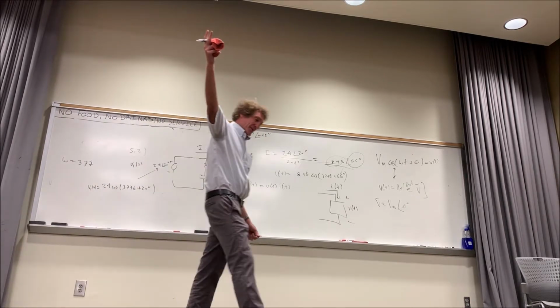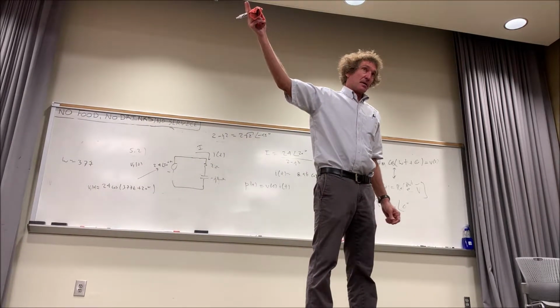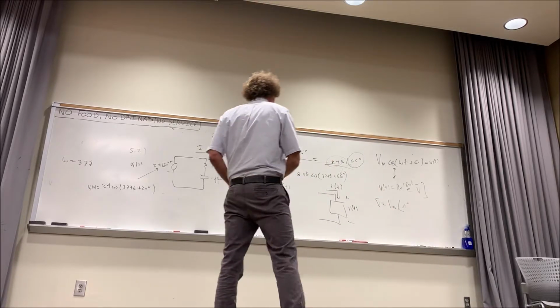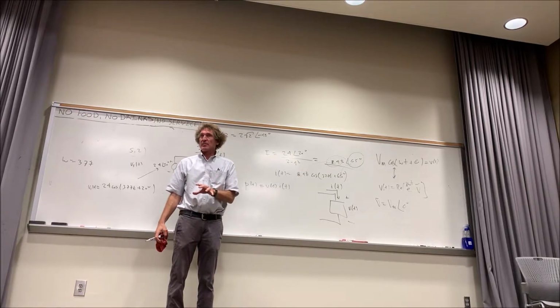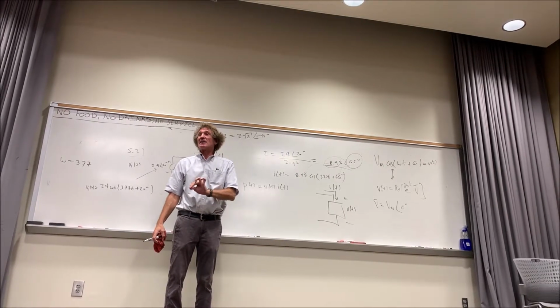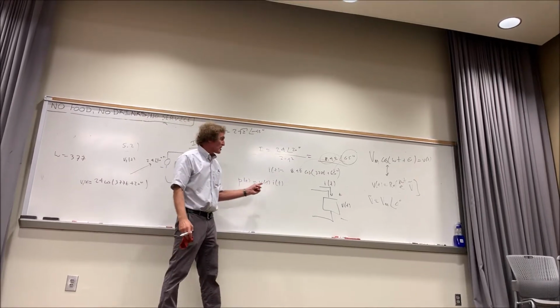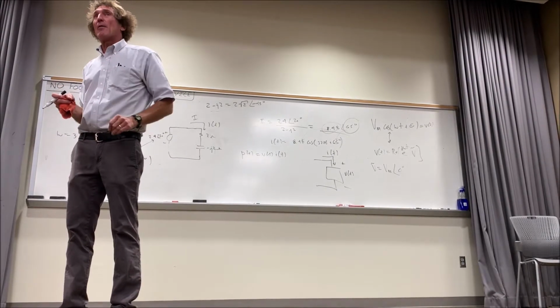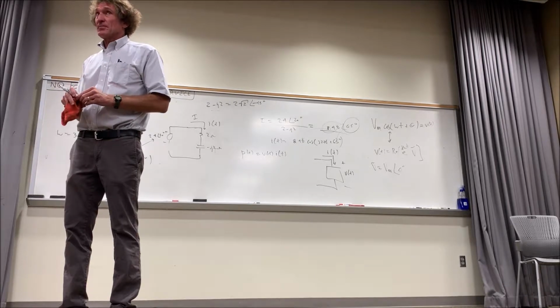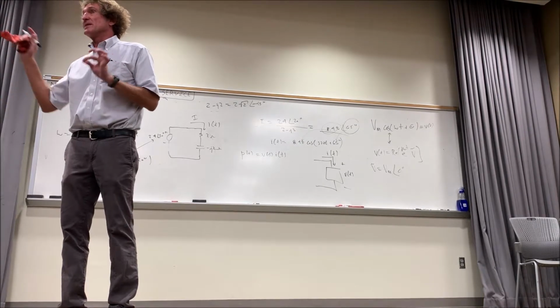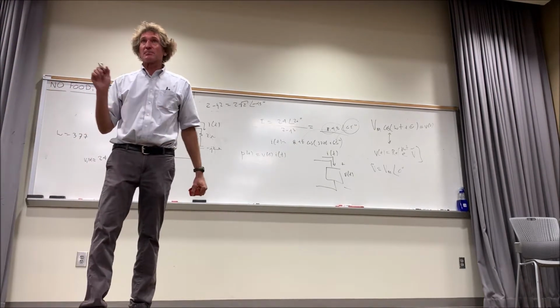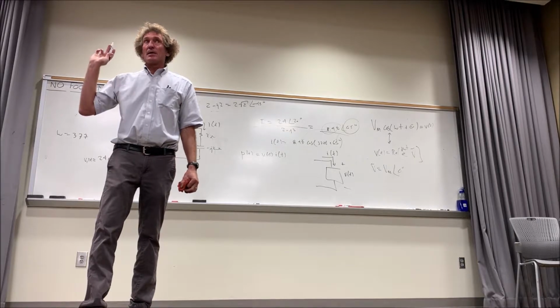Can you just repeat what you were saying about the positive and negative terminals of dissipation power? Well, the way we define power dissipation, that's going to be a function of time, remember this. You take the current going into the positive terminal of the voltage. So this is the voltage V of t. That will be the instantaneous power. But for a capacitor and for an inductor, sometimes it will be positive, sometimes it will be negative, and the net amount is 0 over a cycle. That's important. Okay?